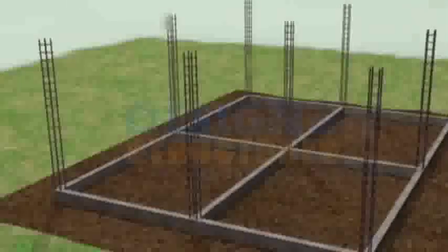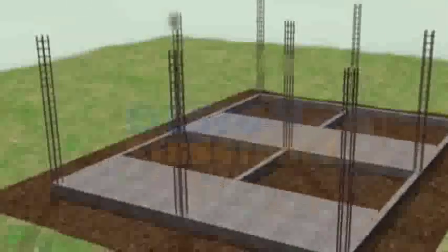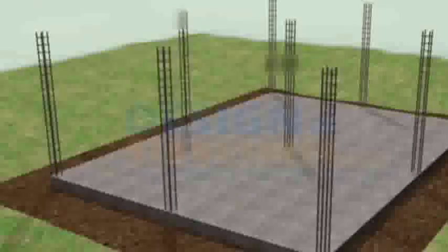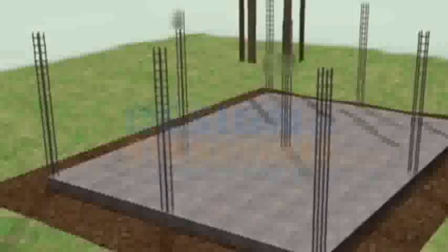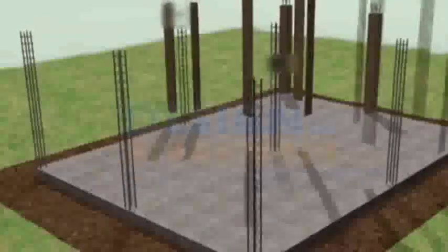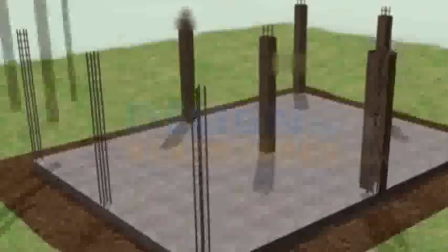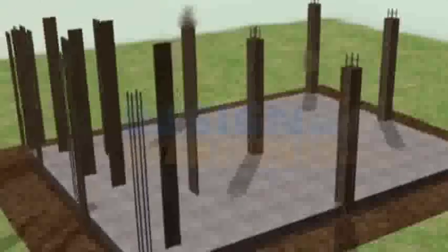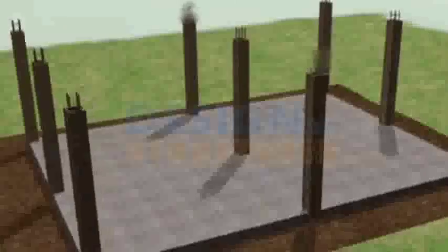Slab concreting. Grade slab requires no reinforcement as it's resting on ground strata itself. Top of plinth beams and grade slab should be at the same level. Column shuttering. Column shuttering should be rigidly constructed and efficiently propped and braced both horizontally and vertically, so as to retain its shape. The shuttering should be set accurately to the desired line and levels and should have plane surface.